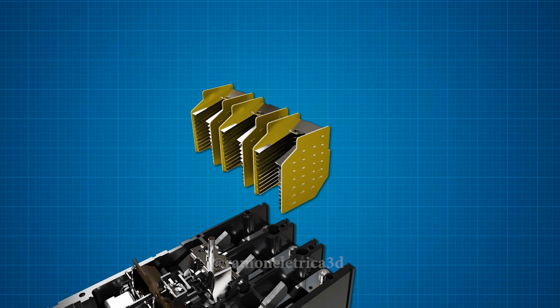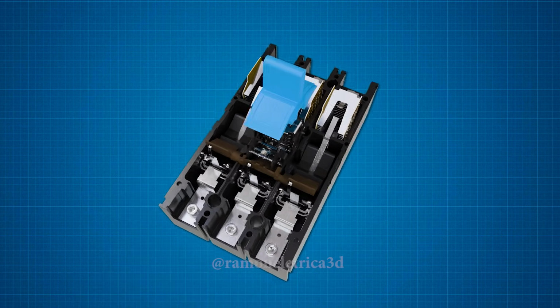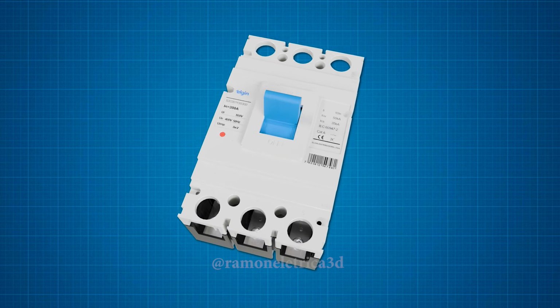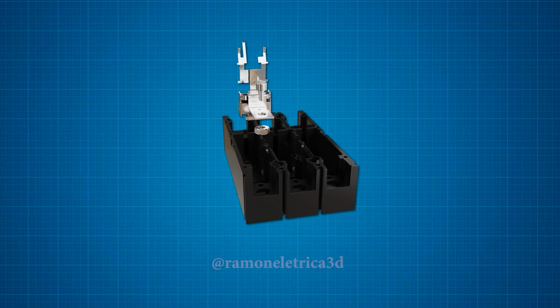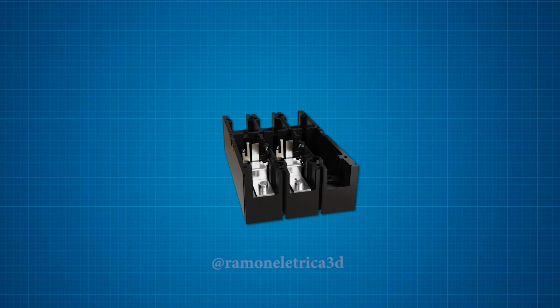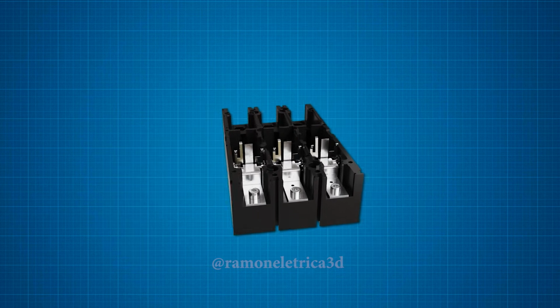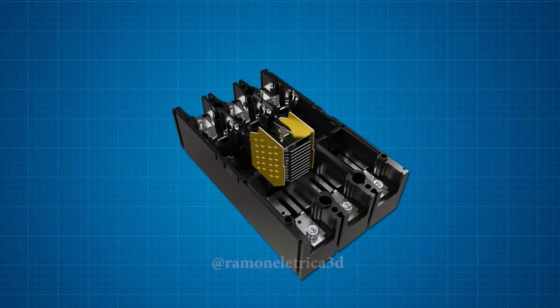With this internal functioning of the MCCB, it becomes clear why it has a much larger structure than an MCB. It not only offers greater mechanical and electrical strength, but also provides much more robust protection for installations that operate with higher rated currents and short-circuit levels. And that is exactly why MCCBs are widely used in industrial applications and distribution panels.